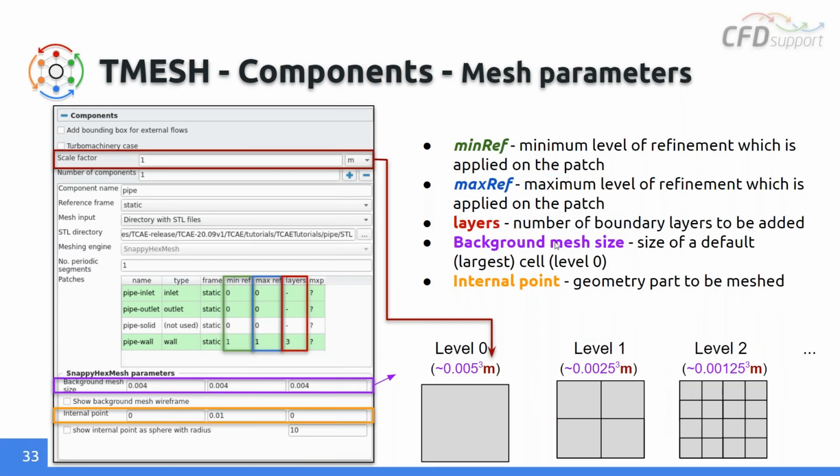So how the meshing works: you define the so-called background mesh sizing. So you define the size of the largest cell in the domain. It automatically defines a box in which our domain is enclosed. It defines all the cells with the same sizing, which we define here, x, y, and z, the direction and size in that direction.